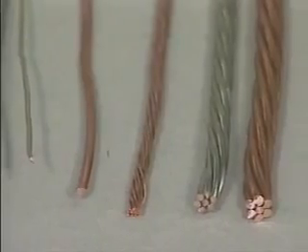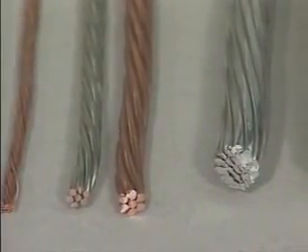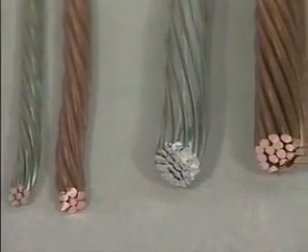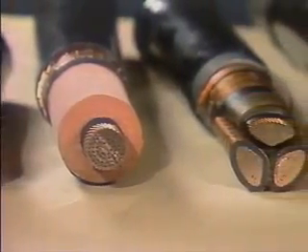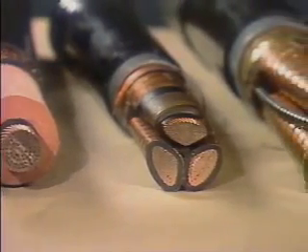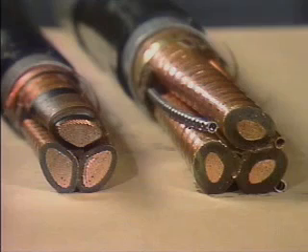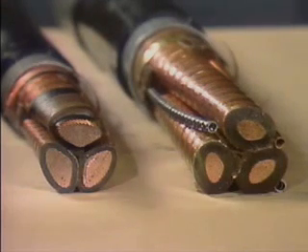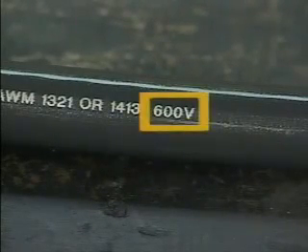The conductors that we've discussed so far are typical low-voltage conductors. That is, conductors that are built to handle up to about 2,000 volts. Conductors that are built to handle over 2,000 volts are constructed differently. That's because they rely on design factors in addition to the thickness of the insulation to handle high voltages. In this unit, we'll focus on low-voltage conductors. That is, on conductors that are designed to carry less than 2,000 volts.